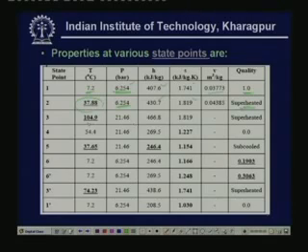Point 3 is the exit condition for the compressor. So, what do we know at this point? We know the pressure, because this is nothing but the saturation pressure at 54.4 degrees centigrade, and we also know the entropy, because this is an isentropic process. So, S3 is equal to S2. From the known values of pressure and entropy we find the other properties like enthalpy and temperature. The temperature works out to be 104.9 and the enthalpy is found to be 466.8 kilojoule per kg.